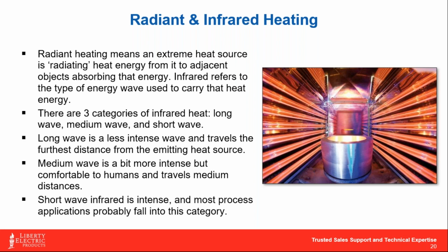Long wave infrared travels the longest distance. It's the most comfortable on human skin, but you're typically not going to find long wave infrared unless it's something that is very, very specific to a material or a process to create a material. But typically long wave and medium wave infrared are meant more for human comfort versus industrial process.